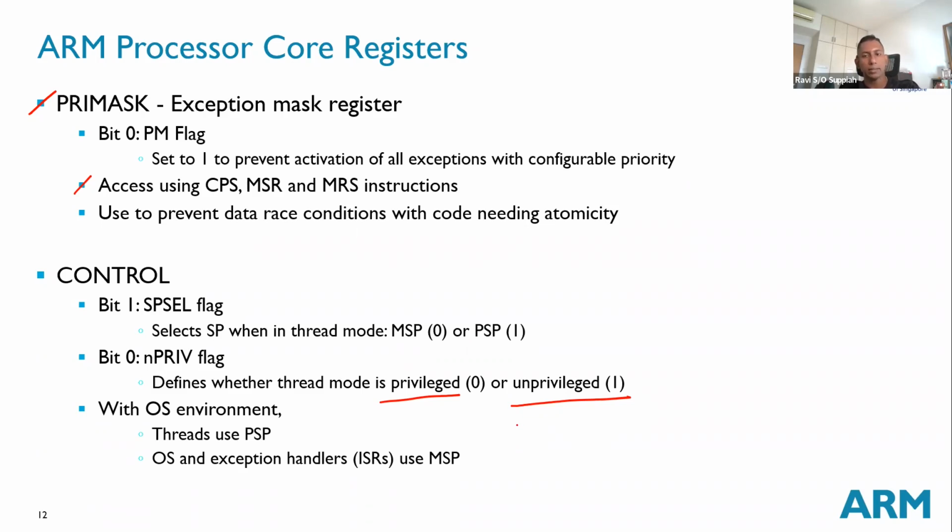This is very applicable in, let's say, your smartphone, where you have your OS that's going to run in privileged mode, but the apps that run on it have to be unprivileged, because you do not want an app to go in and mess with your system settings that can corrupt your phone or hang your phone or things like that. So there is some mode of operation depending on how you configure the processor.